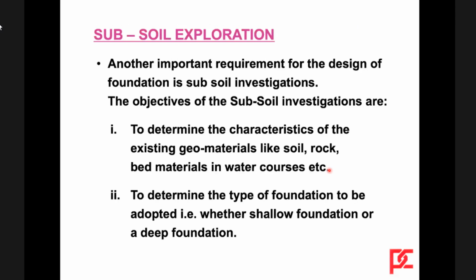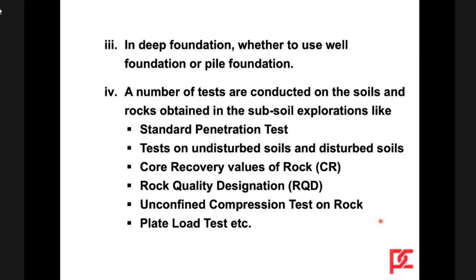Then apart from this hydraulic investigation, subsoil investigations are also required for the design, to determine the characteristics of the existing geomaterial like soil, rock, bed material in the watercourse, etc. And to determine the type of foundation to be adopted, whether shallow foundation or deep foundation. In deep foundations, whether to use a well foundation or pile foundation.